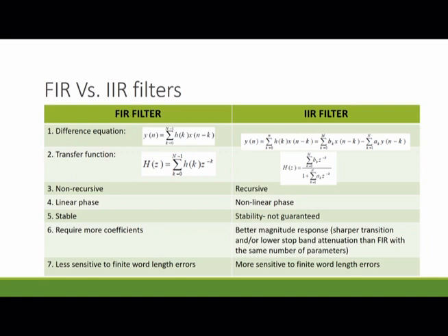The reason is that the filter coefficients are symmetric, and due to this linear phase characteristic, the phase distortion offered by this system is minimal or zero, whereas phase distortion can be expected when we use an IIR filter.